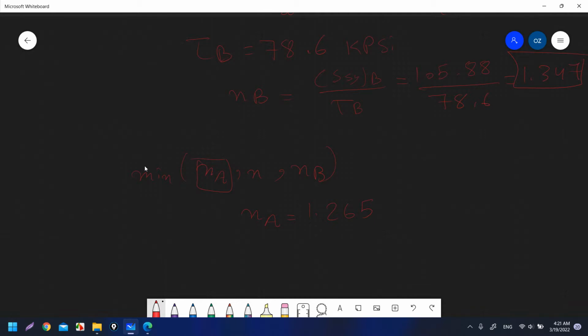That means that at point A, what is happening is bending, right? There is bending and there is normal stress. It means that the spring will fail because of bending at point A first, before point B and the coil, the main body. So yield due to bending of the end hook, because point A at the hook will occur first.